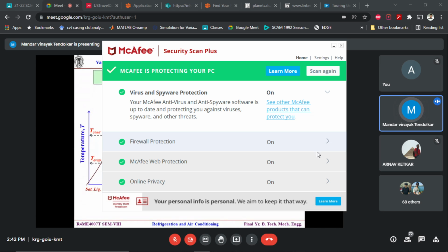Now I introduce this opposite area to that of A2 as A3, and I will say that it is the additional work required. Why is this required? As no work is recovered during expansion. Ours is isenthalpic expansion. Joule's porous plug experiment. If you use the turbine, there will be work generated and you can supply it to the compressor so that your compressor work requirement could be reduced. But if you use a simple capillary or a thermostatic expansion valve, you cannot harness any kind of work from that. Correct?